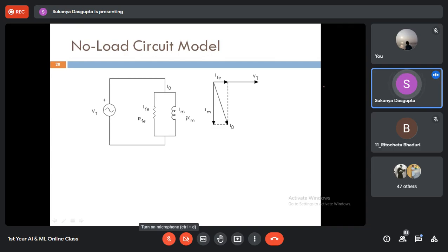That huge amount of voltage that is developed at the secondary winding will be impressed fully across the open circuited terminals. So if any personnel or any other equipment is associated with that site, definitely there will be damage of that instrument or personnel.